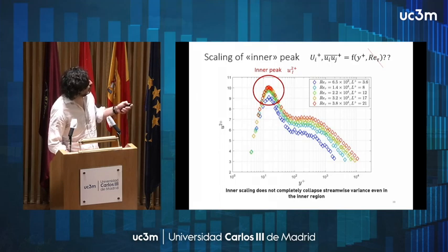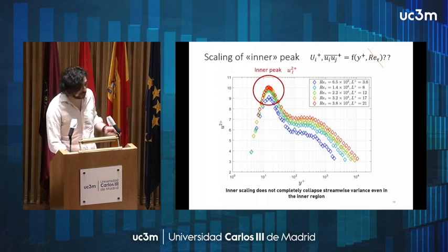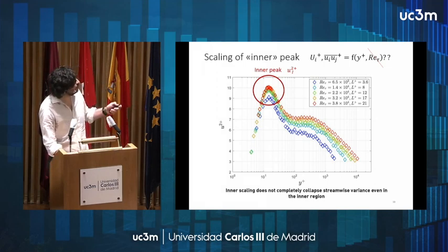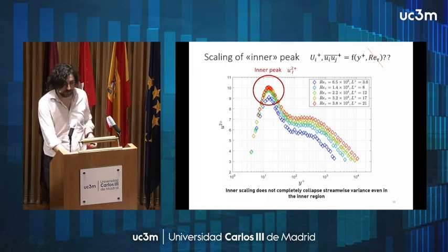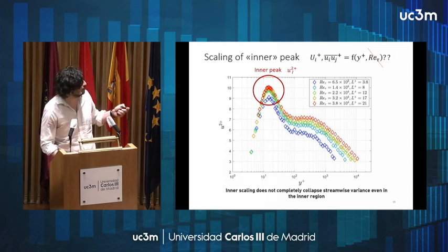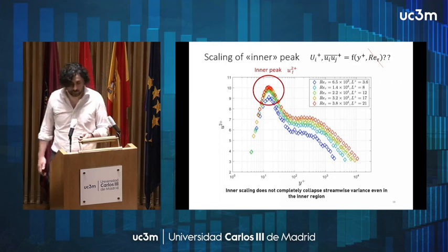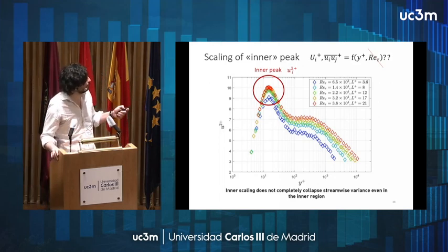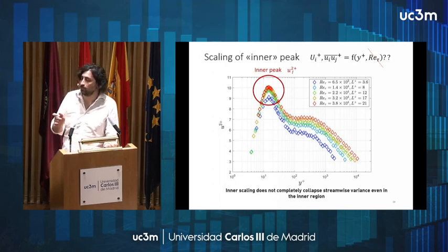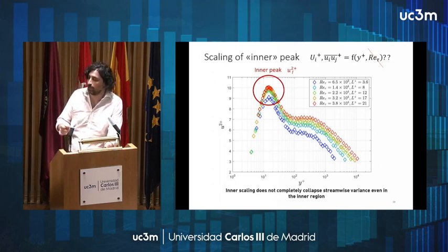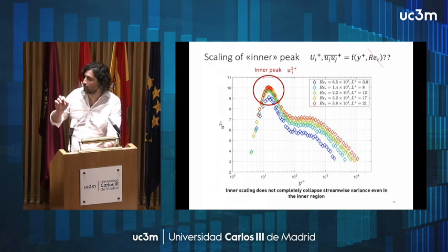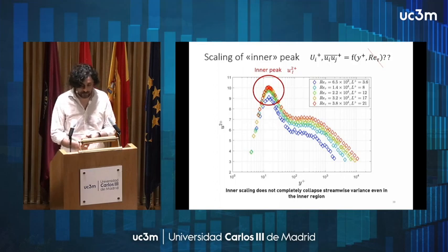This is quite challenging to build, because at y plus 15 we have a really important point in the flow, where the peak of turbulence production occurs. That's where turbulence is produced within the flow. So we are very close to the wall. Y plus 15 means that at high Reynolds number, we are 12 microns times 15, so we are 0.1 millimeter from the wall. So the probe positioning becomes very, very challenging.